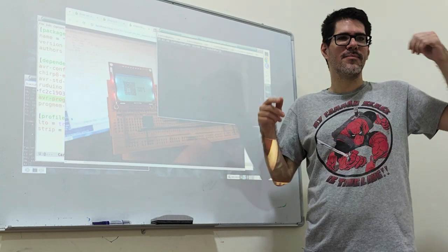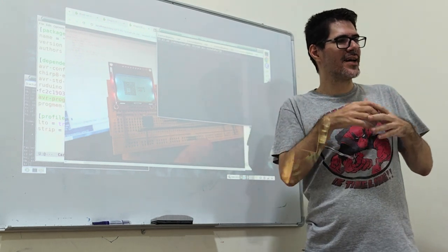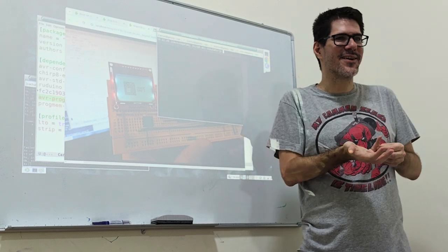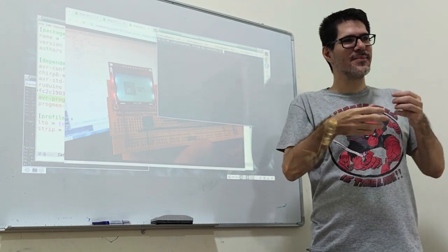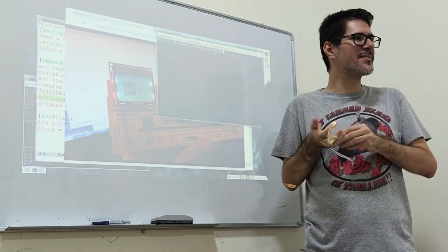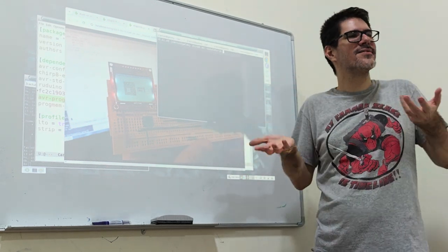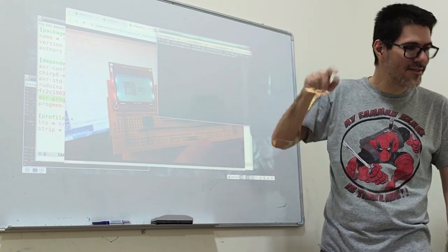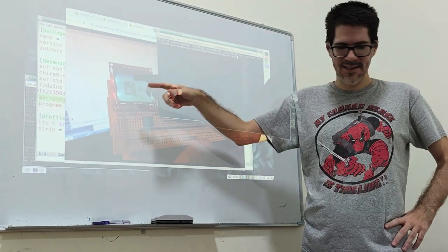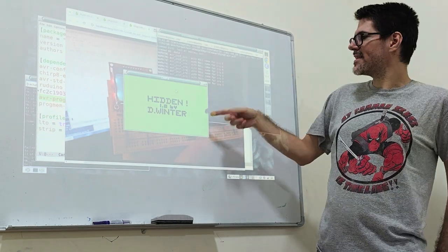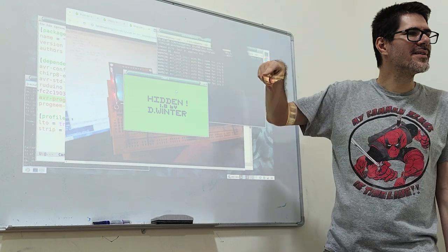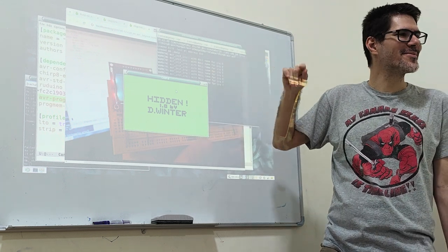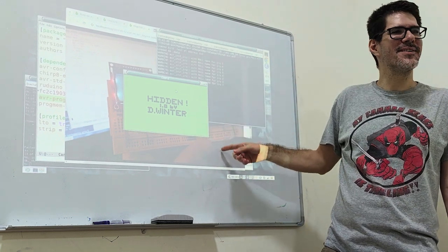This was very important back in 2017, because all the ways that the LLVM backend failed, it was generating some AVR machine code, but not the one that would do the thing that I wrote in Rust. So to be able to see what is going on there, I depended very much on having good emulators. Now it's less of an issue because it really does seem to be working out. But it's still fun that you can compile the Rust version that targets AVR, and then pass it to this thing, which is using the AVR emulator, or simulator, hooked up to some virtual implementation of the same SPI protocol that is spoken by the real serial memory and the real LCD.